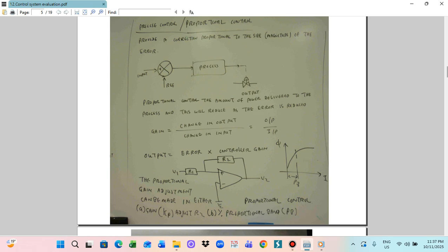So up to here, we're talking about the control system. When we are making the control system, it needs to settle in a very short time. If any change happens, the controller will vibrate. Vibrating means the unstable region. This unstable region needs to be minimized. After some oscillation happens, the vibrations will become stable. So in this case, our controller characteristic is that it needs to minimize the maximum value of the error, minimize the settling time, and minimize the residual error.